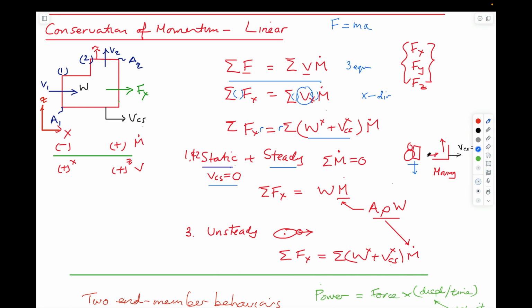And we also would have talked about a moving coordinate system where fluid goes into the system and out of the system and has a finite non-zero control surface velocity, where VCS no longer is equal to 0. In all of these, if they're steady, and we've only talked about steady problems for these systems, then the mass rate in equals mass rate out. That's the definition of steady.